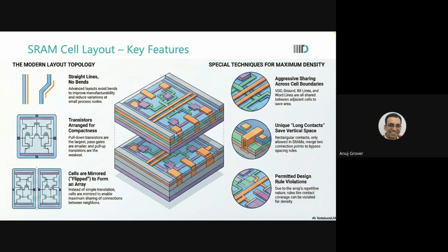Okay? There was a question in the last quiz about which DRC violations we can make in the cell and what the advantages of the optimization are. One correct answer was the minimum metal to metal DRC. We actually did that, because we were not covering the whole contact because of the metal to metal DRC. Yeah. So, look at it like this.